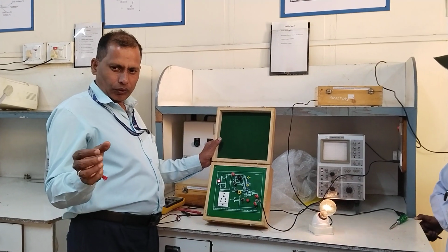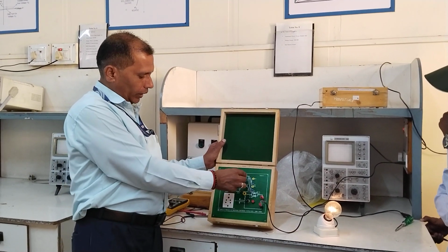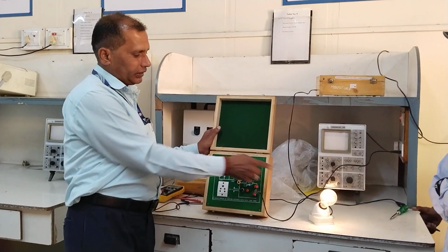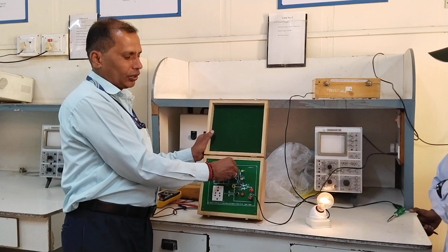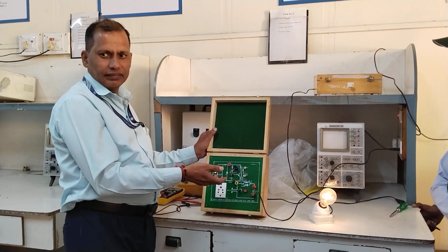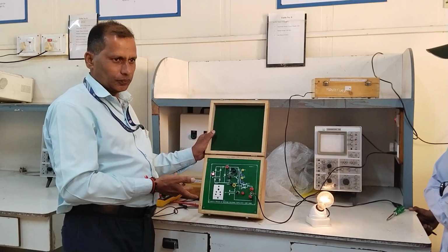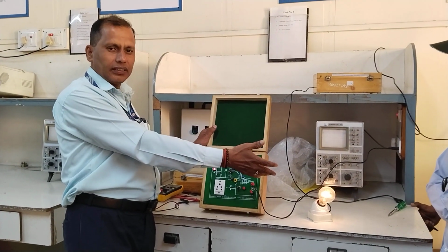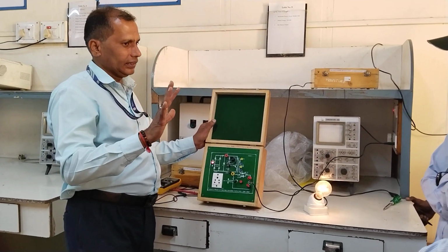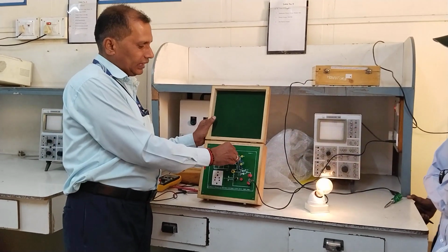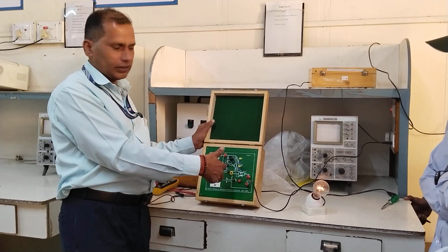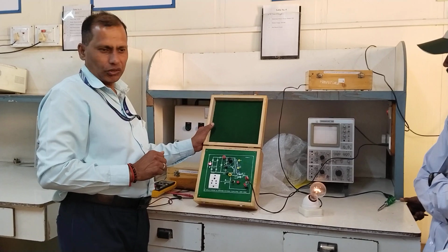So let us look at the observation of this experiment. As you vary alpha, the firing angle, see the effect on the light. You can have control over the light. It is very simple, the circuit is very simple. You can even make a small mini project on this. As you observe the intensity of the light, your voltage is decreasing and increasing. You can decrease the 230 volt and then increase the voltage. At what level you can increase it, you can see using a multimeter, take the observations, and observe the waveform on the CRO.